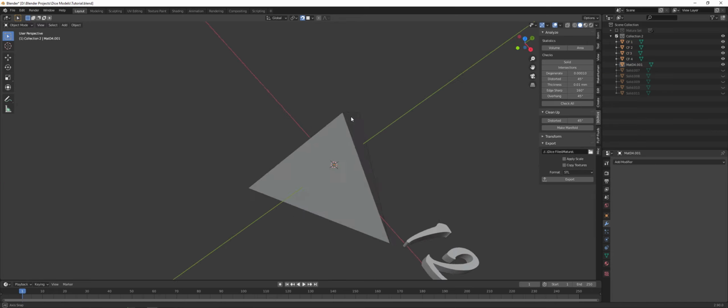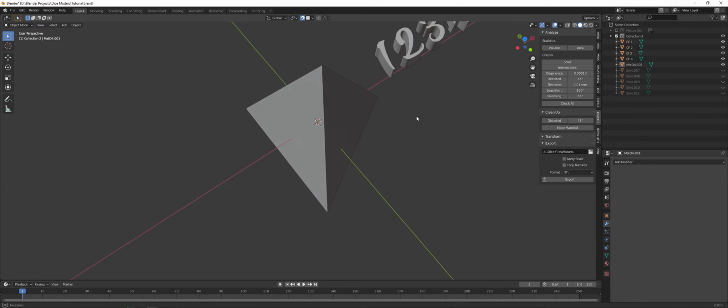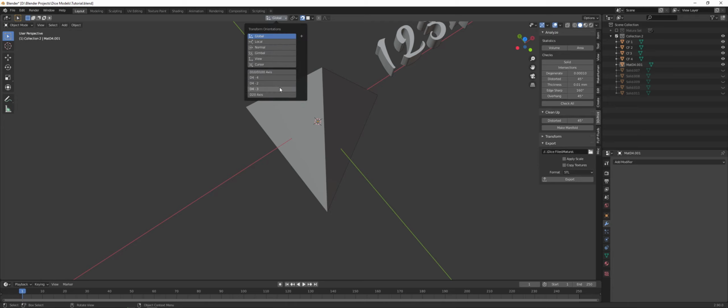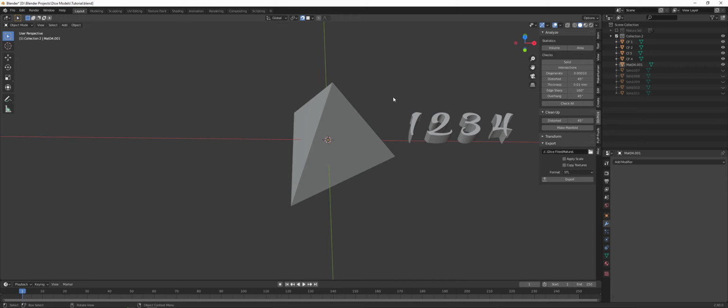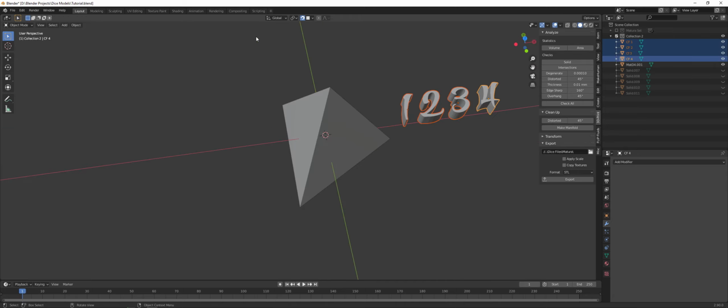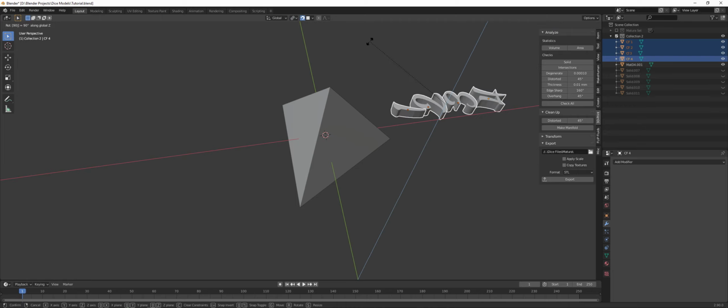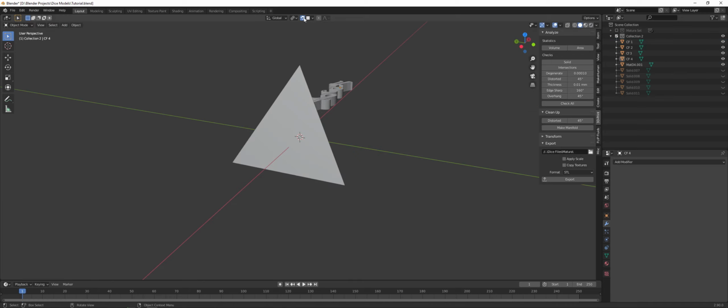So this D4 is actually gonna take a little bit of custom orientations, as you see I have here. So let's go ahead and prepare it for that. So we're gonna rotate all of them in global and individual origins on the z-axis, minus 90 degrees to put them here. Now make sure you have your snap turned on, and you want it to be in phase, snap with closest, and align rotation to target.